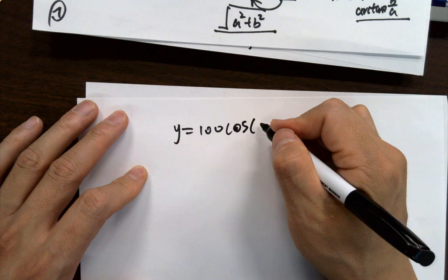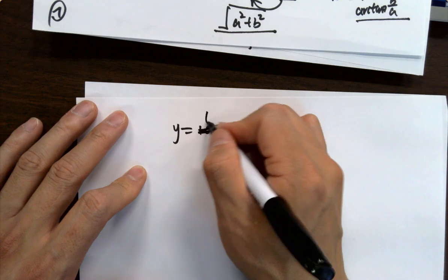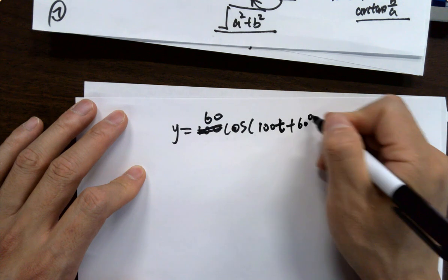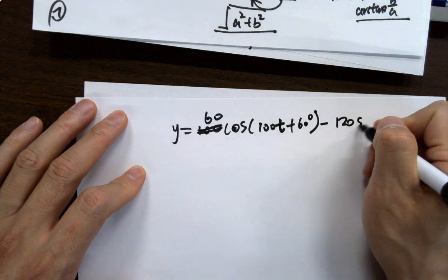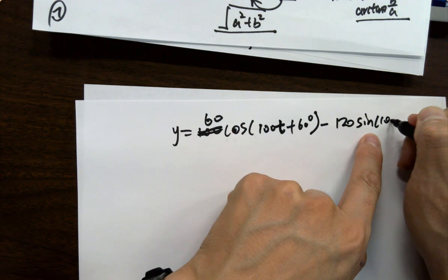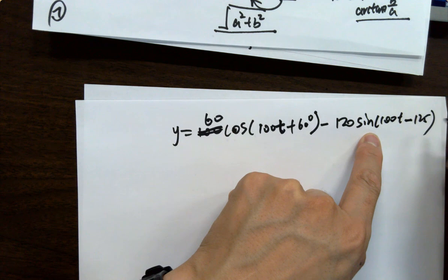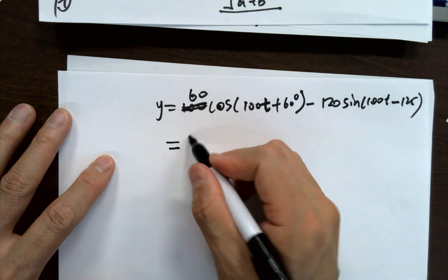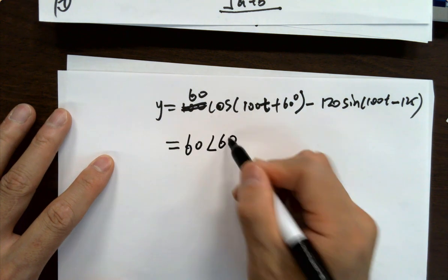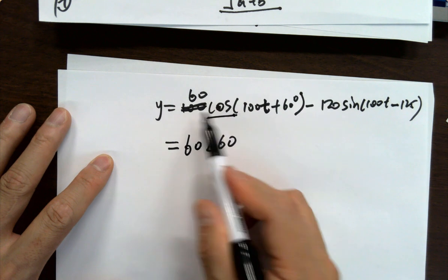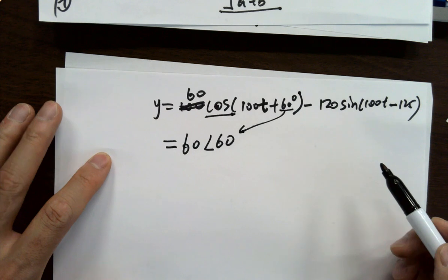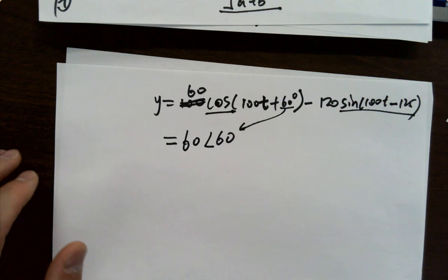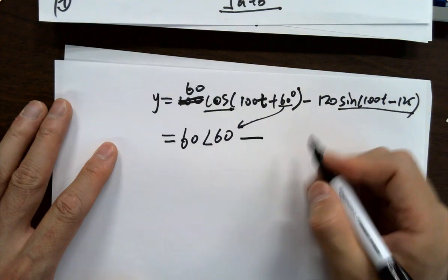And so, what if you see a cosine and a sine wave? Cosine. Use 60. Okay, what about this? 60 what? Since we use cosine as a reference, just directly grab the angle here, okay? And sine wave is not a reference. It has a 90 degree phase shift. So what you want to do is convert sine, because we know sine